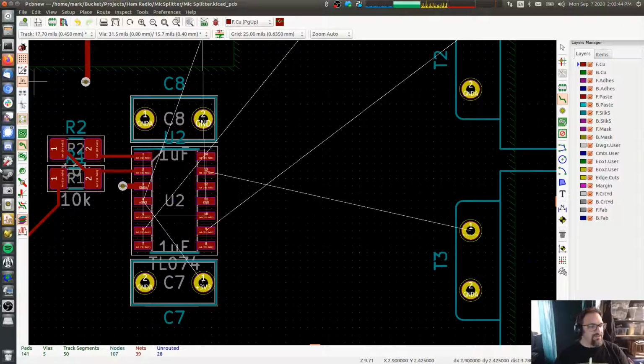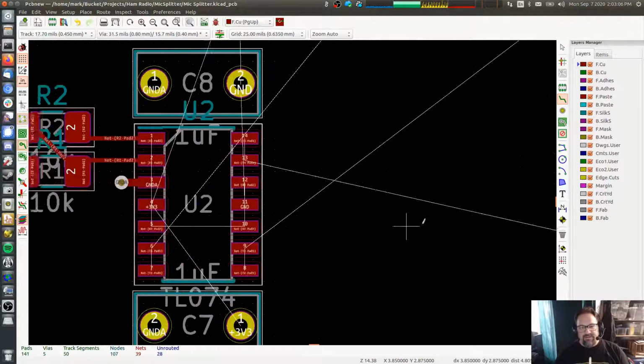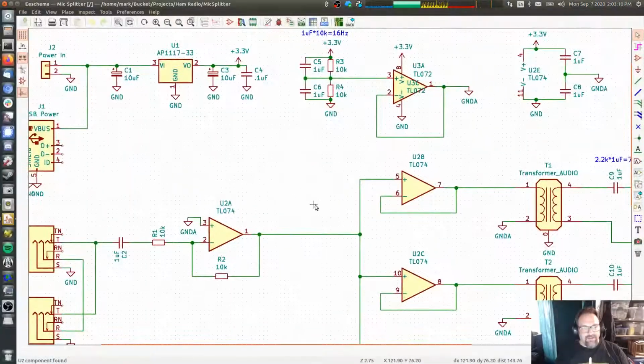Oh gosh, yes. Okay, so all these op amps, look at these cross paths. Like this one, I have to move it up to go to the top one, but I could use the bottom one much easier. And if I swapped this one up to here, then it wouldn't have to cross as many paths to get its output up to its output transformer. These two are crossing, so I could swap these two and they would go to their respective transformers. Okay, so that's easy. Let's do that.